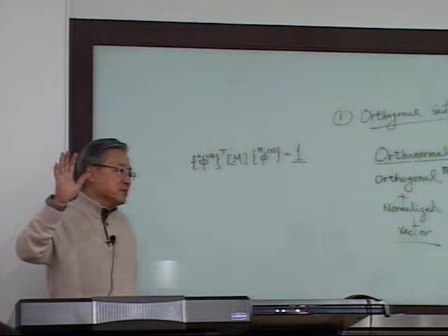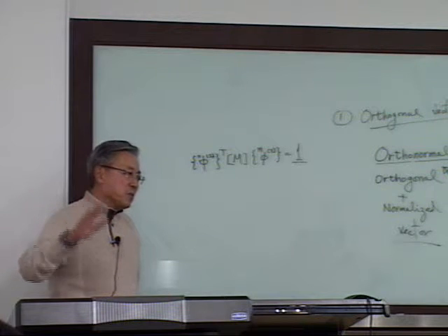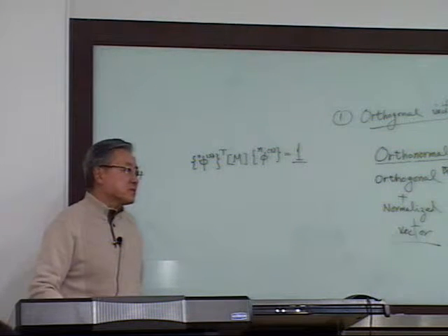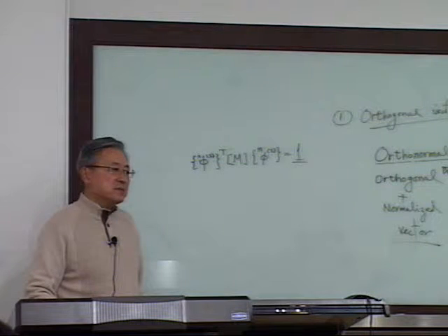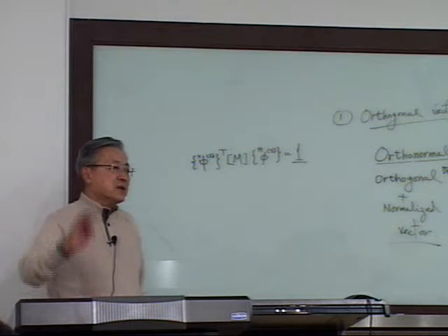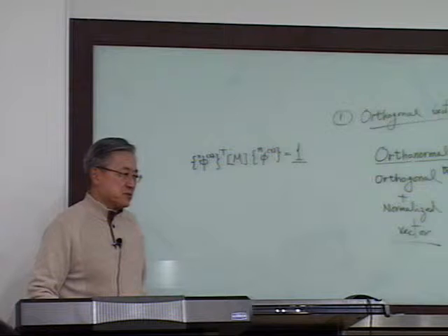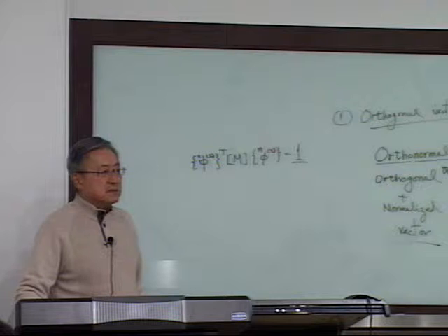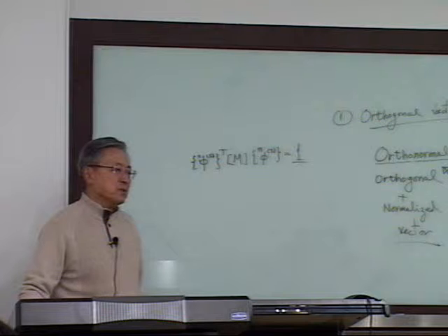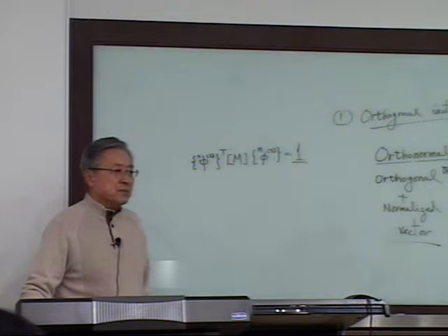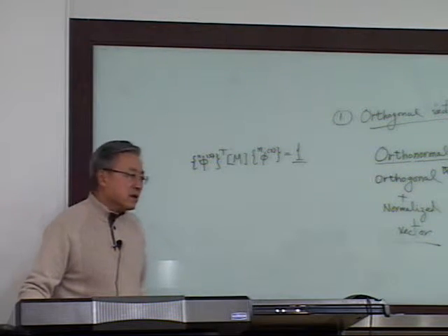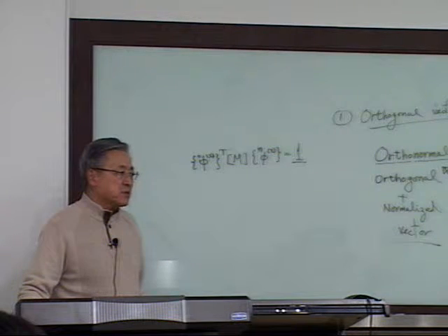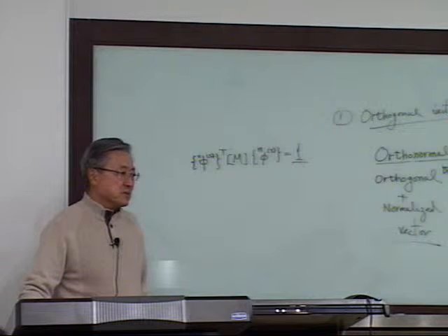The quantities you need for DDAM application from the modal analysis are the natural frequencies, the corresponding mode shapes, and the mass matrix. And to get all that, you can use any available commercial code, that's fine, or MATLAB, if you can set up the eigenvalue problem yourself, vice versa. Okay.